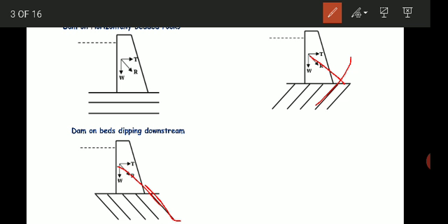So the resultant of the weight of the dam and the pressure of the reservoir water acts parallel to the bedding planes. So this endangers the stability of the dam. That is, the dam may undergo sliding along the bedding plane. Okay, and if the water which is percolating through these bedding planes gets recirculated to the reservoir, that is fine, but if there is a leakage, it will go on the downstream side. Okay, so the purpose of a dam is what? To store the water, but here the water will not get stored.